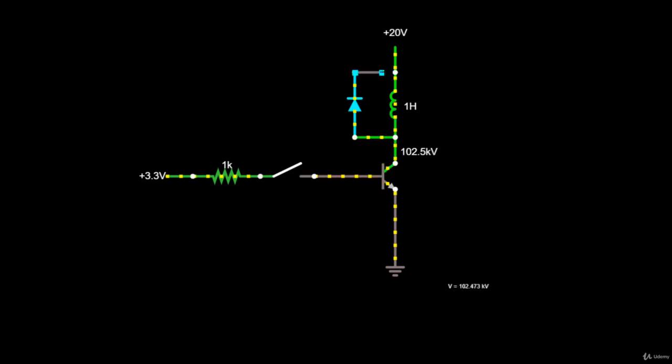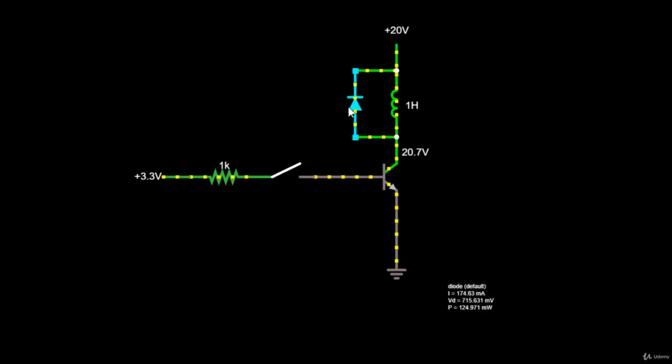There are more types of diodes that we will learn about in the future. For now, just remember that flyback diodes are used for protection against this back EMF voltage spike. You can look at it as a regular diode. Now, the basic idea behind the use of a flyback diode is to provide an alternative path for the inductor for its current to flow.